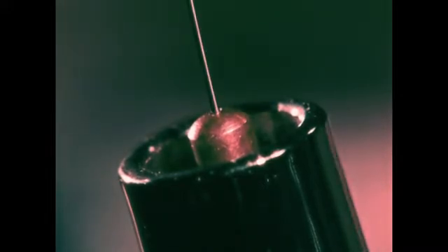The short-circuiting metal transfer method is simple to set up and use, but the knowledge behind each elementary step is important. Let's consider the 6th step, which concerns very basic operator performance. The welding current is transferred to the electrode wire by the contact tube. The contact tube should extend slightly past the edge of the gas nozzle. If it is recessed into the gas nozzle, spatter accumulation could develop and seriously disrupt the gas flow pattern. A recessed position would cause longer wire extension. Correct wire extension should be about 3/8 of an inch from the end of the contact tube.